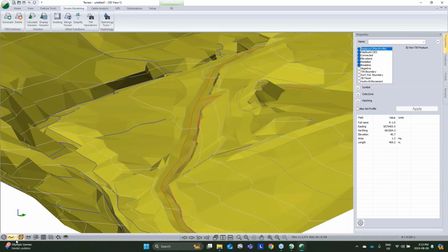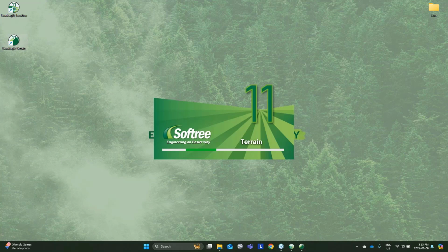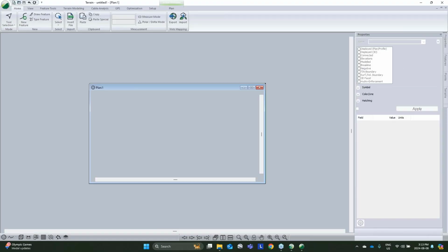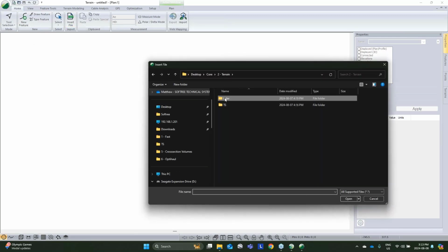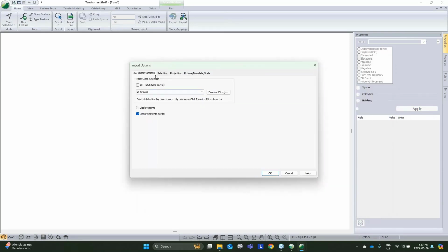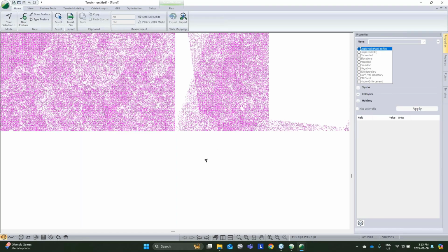And with this, even with all the points to make up our contours, we've got 9,000 points. If we compare this to a LiDAR data set, we can largely ignore a lot of those properties and still get a good surface. And with that, it comes down to the fact that rather than relying on break lines to get a surface to do what we like and having points measured at certain important spots, we're just going to beat it with a lot of points.